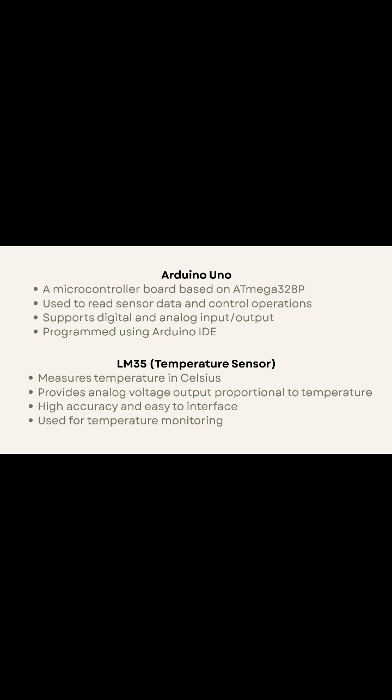Arduino Uno, a microcontroller board based on ATmega328P, used to read sensor data and control operations, supports digital and analog input or output, programmed using Arduino IDE. LM35 temperature sensor measures temperature in Celsius, provides analog voltage output proportional to temperature, high accuracy and easy to interface, use it for temperature monitoring.